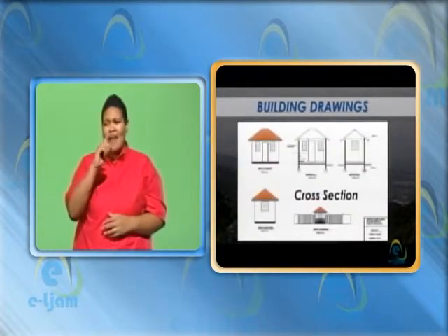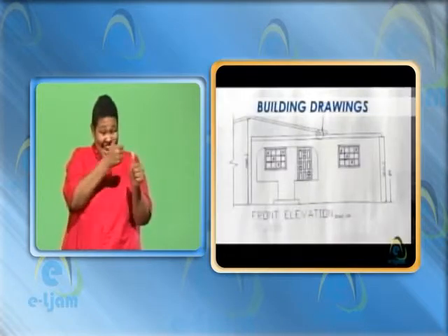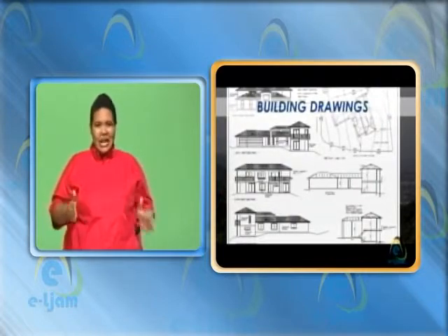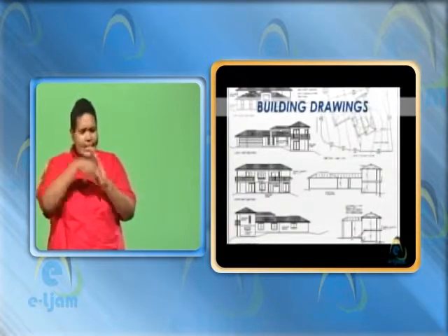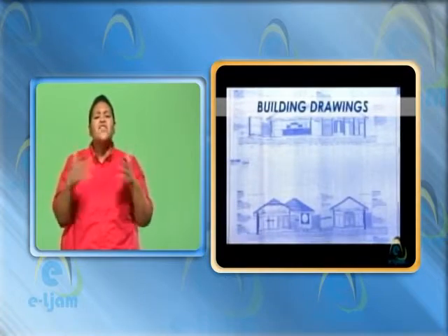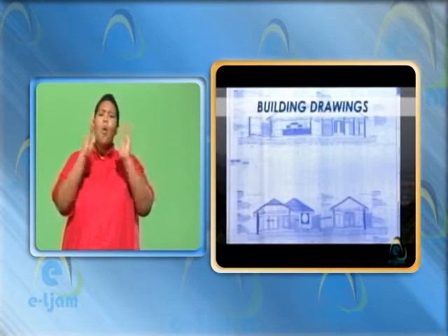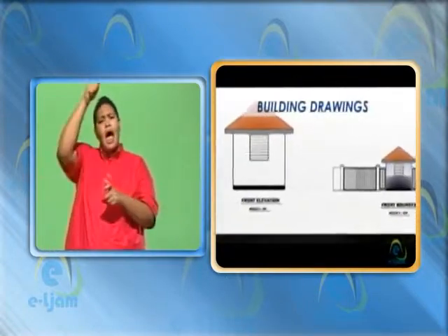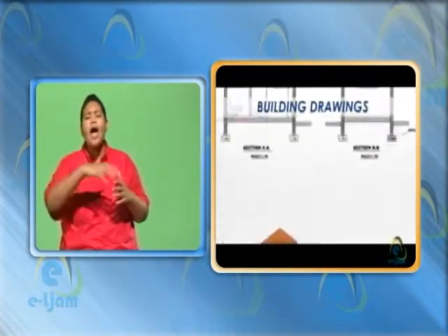Elevation is a set of plans that include 4 elevation drawings, one for each of the front, rear, and 2 sides of the building. The elevation view is a completely flat view. The elevation details the building height, the exterior materials used, including finishing and roofing. It helps give the prospective owner an idea of what the home will look like. The elevations specify ridge heights, the positioning of the final fall of the land, exterior finishes, roof pitches, fence locations, and other details.